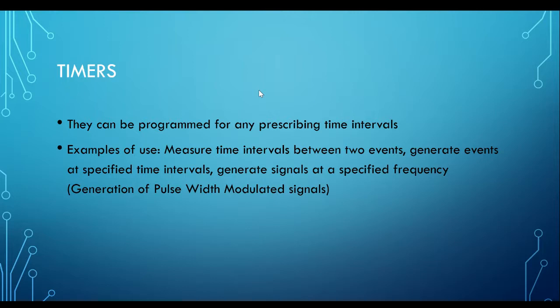Okay. So the timers can be programmed to check the status of sensors at a certain time interval. Let's say, for example, you want to check at 1 second intervals. You need to know how to manipulate the timers that are available. There's only one source of clock, which is the oscillator. You only have one oscillator in your embedded system board, and it is probably about 20 megahertz or so. Now, how can you manipulate this clock oscillator to give you a 1 second interval?